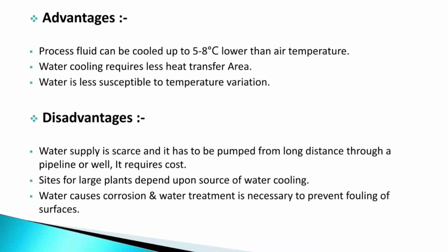Then the advantages of the water cooled heat exchanger. The first advantage is that process fluid can be cooled to 5 to 8 degrees centigrade lower than air temperature. The second advantage is that water cooling requires less heat transfer area, and the third advantage is that water cooling is less susceptible to temperature variation.